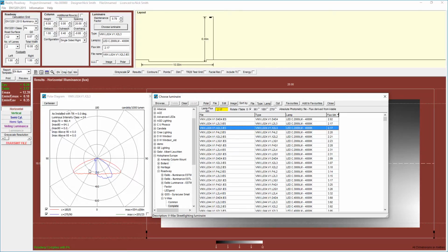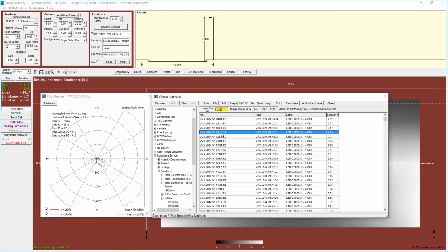The red distribution shows the amount of light that's parallel with the curb, and obviously you lose the forward throw in getting the sideways throw, or towing the lantern in and out, as we often call it. So you can see how between these particular luminaires the distribution here is coming slightly lower away from the center, and therefore you'd expect that value to be higher.